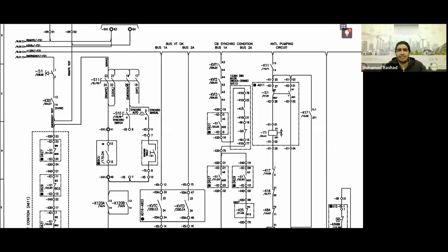And if you haven't selected the emergency mode because the PCU failed, the DC dropped from it, whatever the case, you will start to bring a trolley with it. Meters: 1 to measure voltage difference, 1 to measure angle difference, and 1 to measure frequency difference. You look at it, which is the synchroscope, and you are the one who looks at it in the end. When synchronization happens, you press a push button to close.